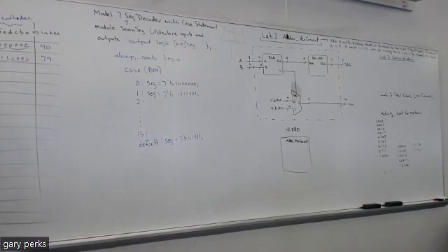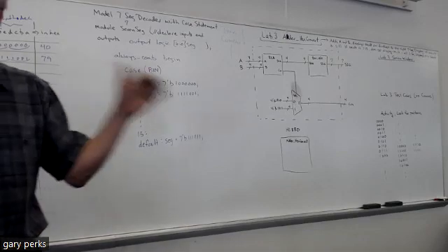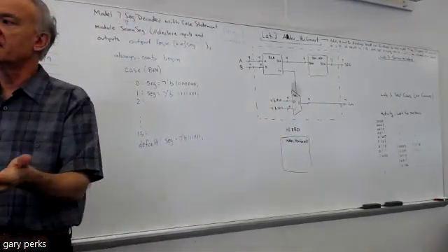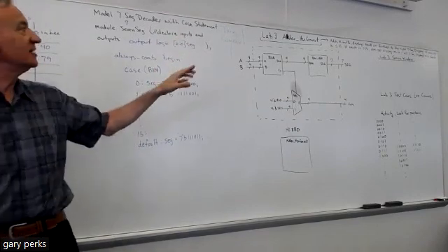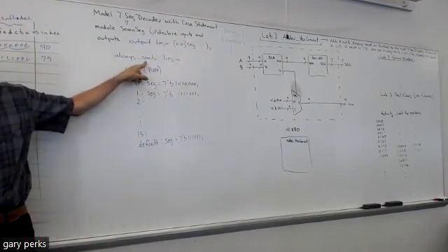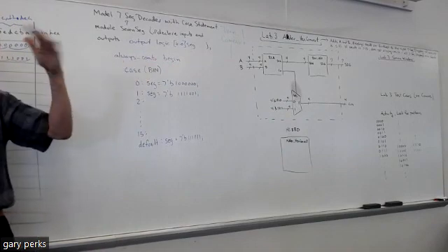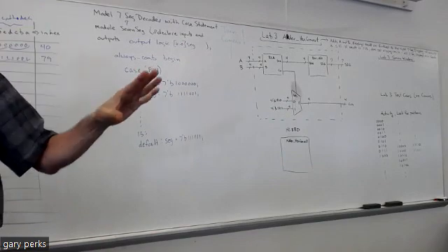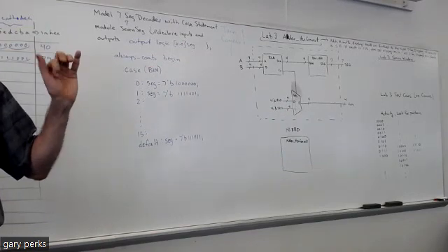But the reason I wasn't worried about it is because the most common way that we create a latch when we want one, which we will in a few weeks when we talk about memory, is you do an if statement without an else. So you're leaving the else out on purpose because it's creating memory, which is what you want. But right now we don't want memory because everything is combinational. Remember, COMB stands for combinational, and combinational is logic circuitry that doesn't have memory, so therefore it doesn't have latches. So you don't want latches.